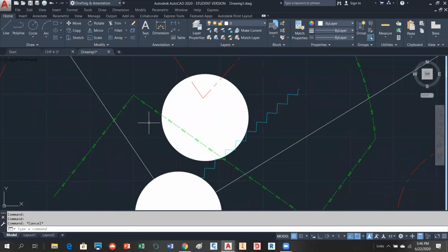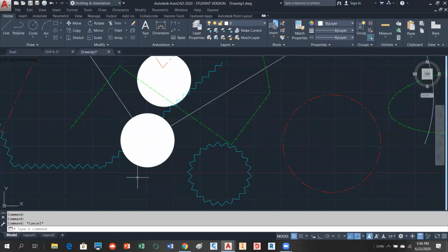Can you see the objects on top of it? Yes. Okay. This is not the same thing as transparency, but it is a way of handling things, because as objects are created, even though they're exactly in the same Z value, there's a time differential between when one is created and the other one's created. And the last object you create is always sitting on top of the objects that were created earlier. So by swapping the draw order, what you can do is manipulate that. If you plotted this right now, you would actually see these guys coming through that donut, whereas you can see this one's covering them up.